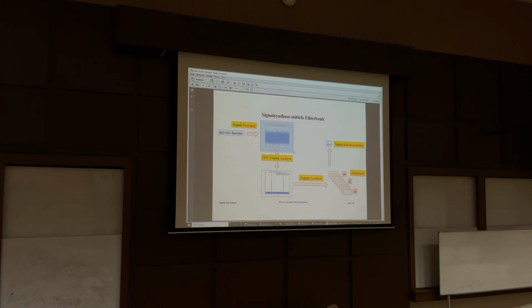Therefore, the first thing you do, we make an FFT analysis. So we look at the spectrum, as we did before. And with this signal here, for example, we get something like that. Now we see, okay, there is a spectrum here. There is one huge amplitude, there is a lot of noise, and there's another huge amplitude. So we know that. And because of this knowledge, we see, okay, the noise is a component which I don't want. That's a component which is an offset, a distortion of the signal. I don't want that. So I want this amplitude or this frequency and this frequency.